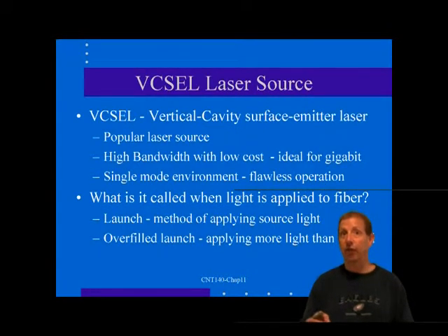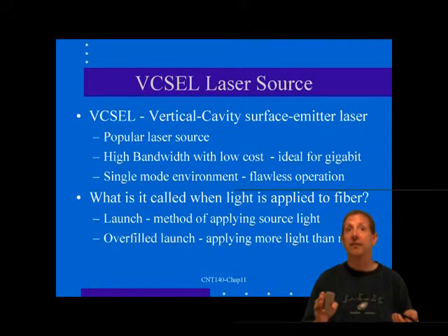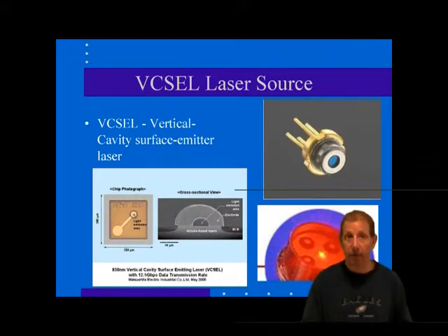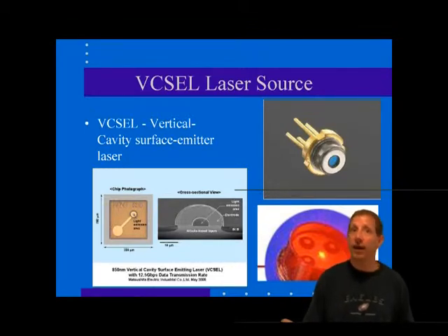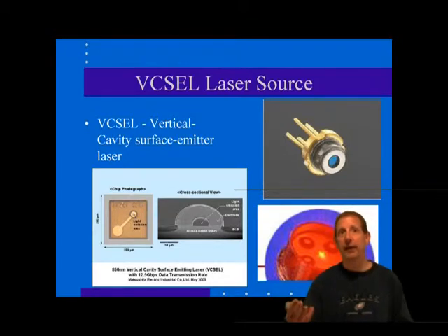No system can tolerate an extra 2 or 10 dB of loss. Worse yet, minor deflections of the fiber, which might be caused by mechanical movements or even temperature changes, can cause the link problem to be intermittent. Two solutions exist to what has been dubbed the VCSEL problem. One is to get better fiber. Certainly, if you're installing new cable, this is the best option. You must be sure that the fiber cable you specify is rated for laser operation as well as extended bandwidth, the bandwidth distance product. Such fiber is often called gigabit ready or laser compatible.